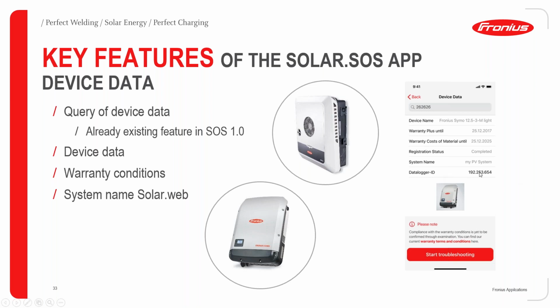And then you have a link directly to the data logger ID, the IP address for the data logger ID. But of course, you cannot reach it remotely. You have to be in the same network as the inverter to work with this ID. Or maybe you can ask your customer to open the port forwarding in his router. Then you can access this PV system remotely. But that's a different story. You can always contact our tech support for further help on these topics.